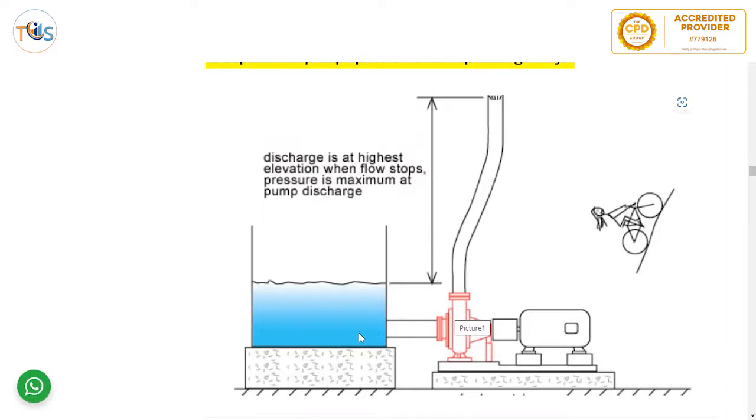If it is not 0, it's coming from another pump, so there is some pressure there, or it's from a tank at height, then this pressure minus this pressure, the inlet pressure minus the outlet pressure, would be the discharge pressure or differential pressure.